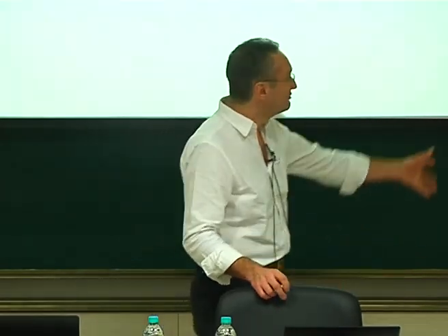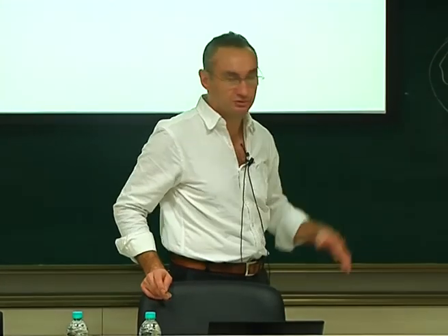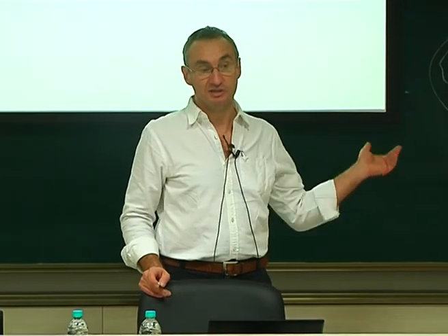It means that in my crack, if I do that, ahead of the crack I will always have ends of dislocations to accommodate the plasticity I want, so it will automatically, locally, generate Frank-Read sources and so on. The thing is that we don't do that because it takes time. Usually we are too lazy, so we prefer to put those Frank-Read sources. But I agree that this is not correct. Nowadays we have beautiful computers, we could do better, and I think we should do such a trick. I haven't seen anybody doing that, but we should definitely do it.